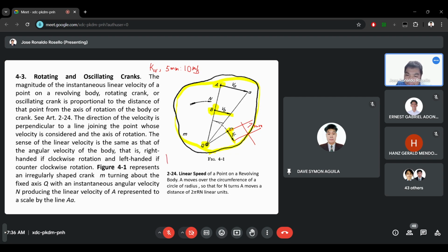So velocity C is equal to 7 mm times 10 meters per second over 5 mm. Again, this velocity scale is given by the designer, so it depends on you. It may depend on me depending on the exam. On the exam, definitely I will give the velocity scale. But for the design plates, you will have to decide on your own. When we multiply the velocity C by the velocity scale, the unit mm cancels, and we will have 14 meters per second.